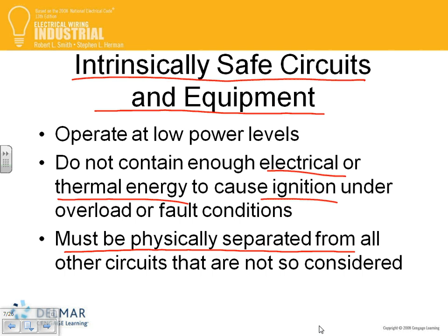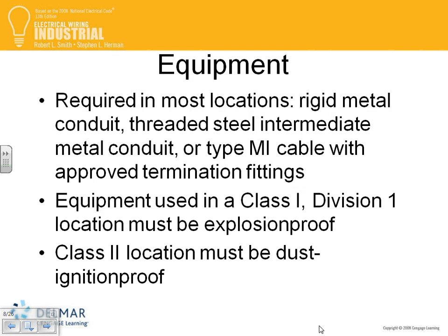Any questions, guys, about that one? And the good thing about using an intrinsically safe system is you don't have to have rigid and all this stuff, because they don't have energy in them. Okay, all locations, guys, class 1, div 1 locations need, when you wire, Brad, when you start working, this is what you're going to be wiring with.